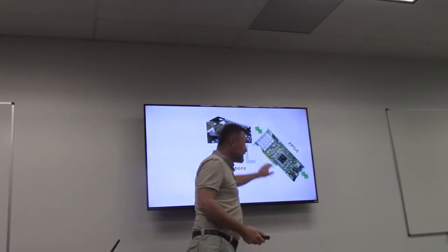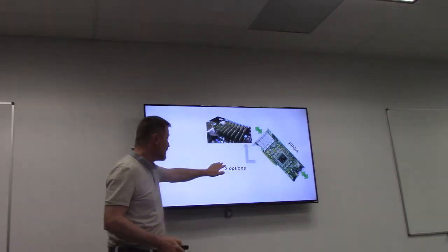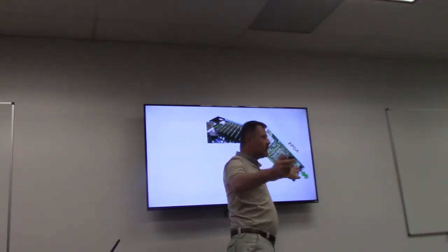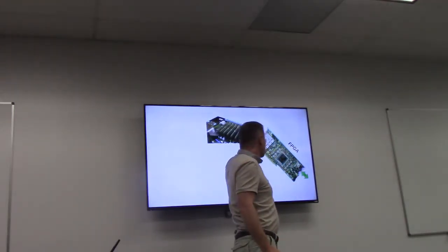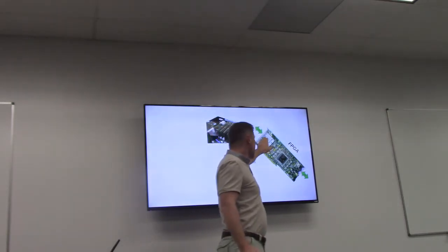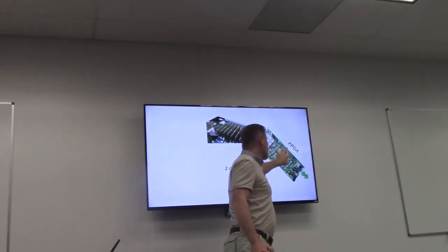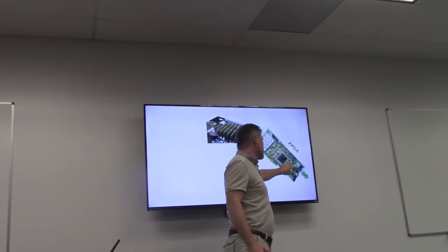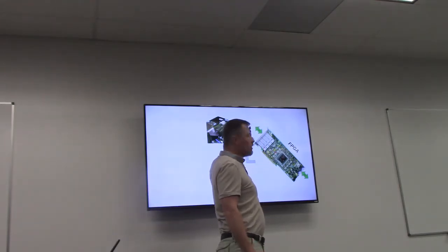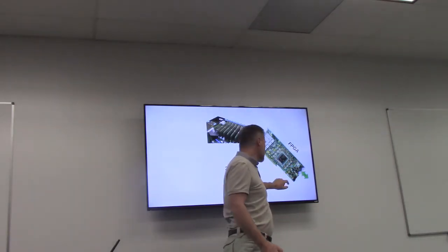So you have two options to accelerate a function. Either you take an FPGA, which will offer new IOs, and my colleague has spoken about that. This is very interesting to bring IOs to your computing system, like very fast Ethernet, local memories. We will see that this one doesn't need memory, because the speed and the latency to reach the processor makes the host memory visible from the FPGA. So we don't need any more DDR on the card, which is very, very interesting.